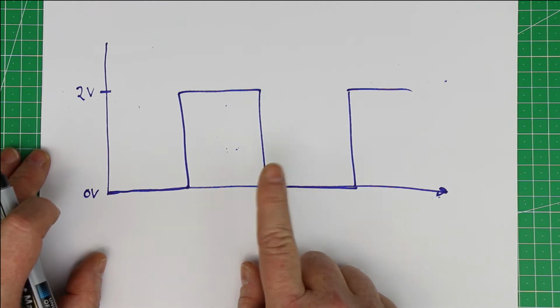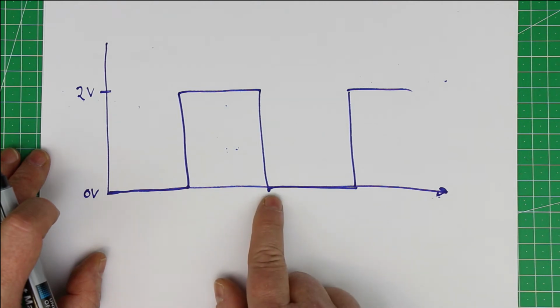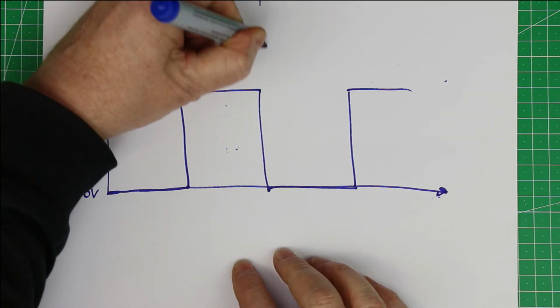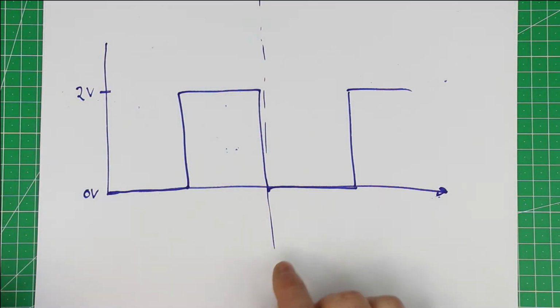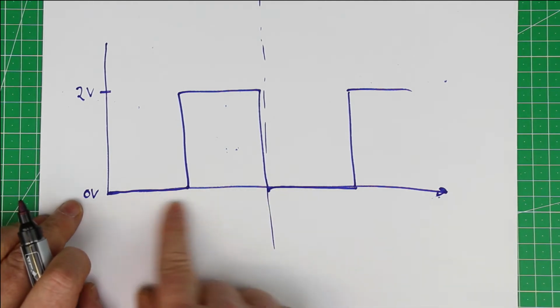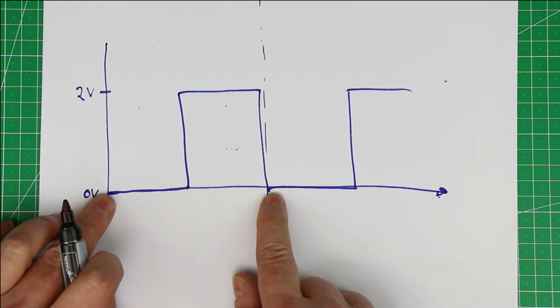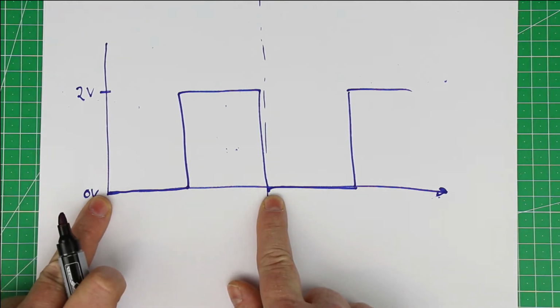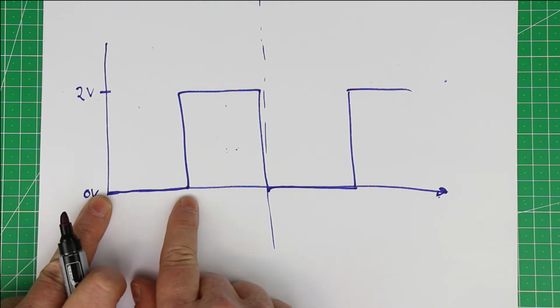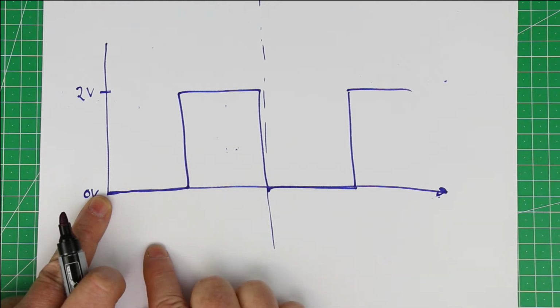Well, let's make the calculation, and it's straightforward. If you have periodic signals, you only have to calculate one period, which means we only have to calculate the squares of the voltages from here to here, and we only have to take the parts of the signal where the amplitude changes, which is quite simple here.